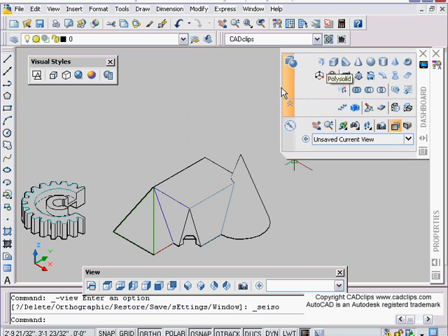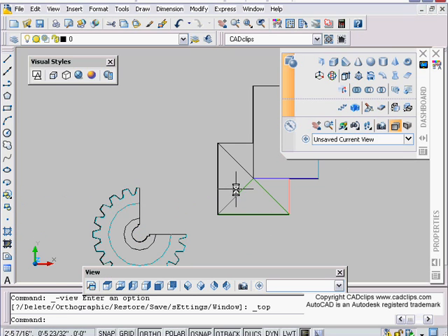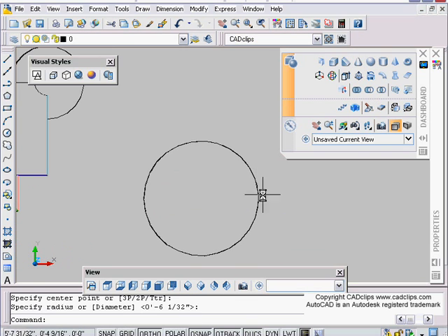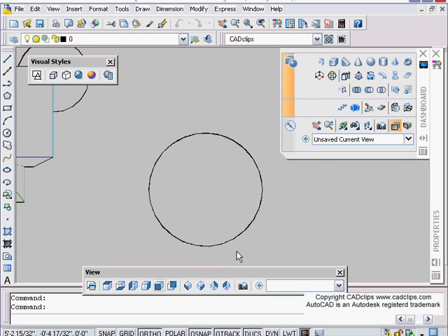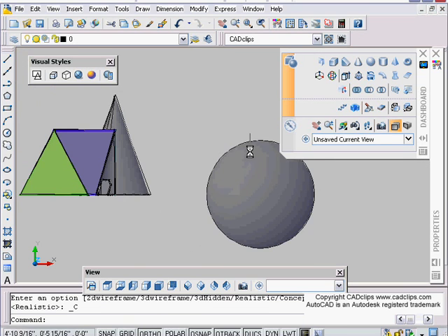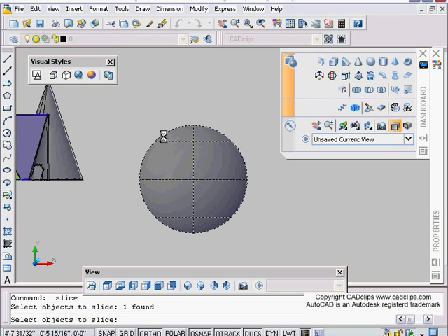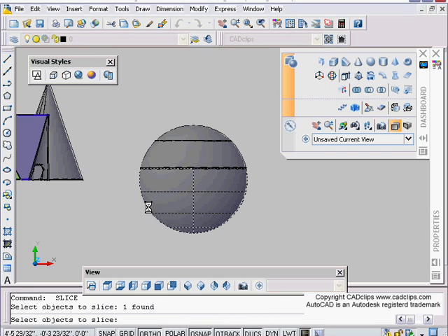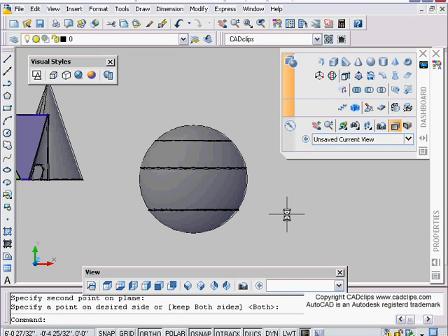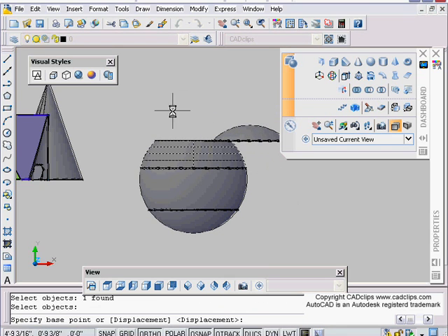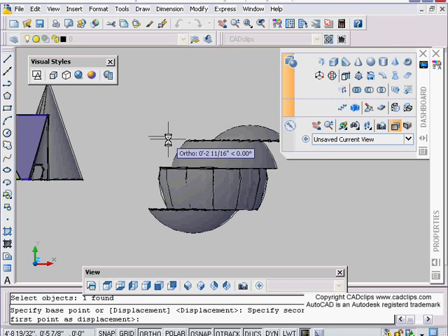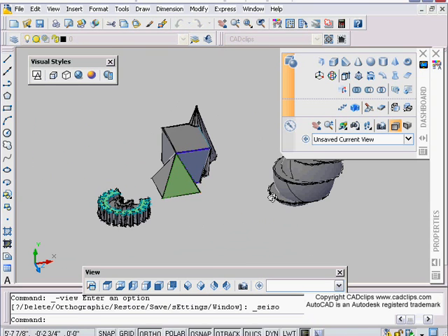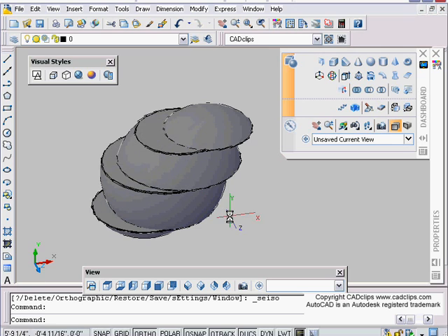Oh, I wanted to slice up a sphere, so let's try that. Okay, back to the top. The quickest way to slice and dice, a good example, is I'm going to draw a sphere over here. I might even look from the front view just to have a different angle. Doesn't really matter. Then slicing here, enter, pick, pick, enter, enter, pick, enter, click, click, enter. Then we could just take this, for instance, and move this aside. Maybe go back and look at that in our 3D view, just as an example of the quickest way to use the slice command.